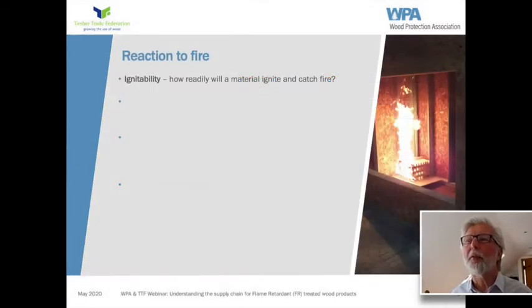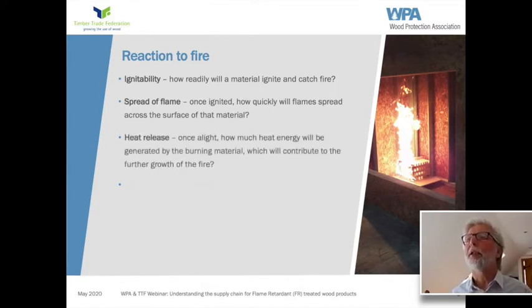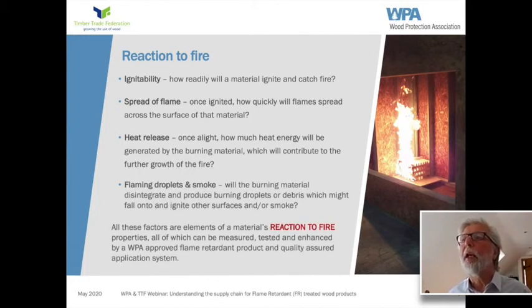So just to sum up on that, reaction to fire properties are the ignitability, spread of flame, heat release, and then flaming droplets and smoke. And all of those factors are elements of a reaction to fire. And we can measure those, and we can test them, and we can affect them using treatments, and we can actually certify a material, give it a fire classification report to explain what its reaction to fire properties are.